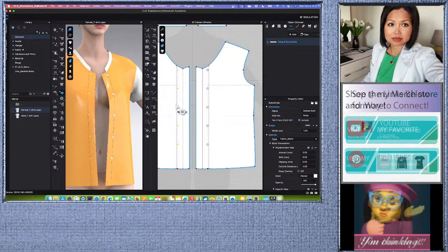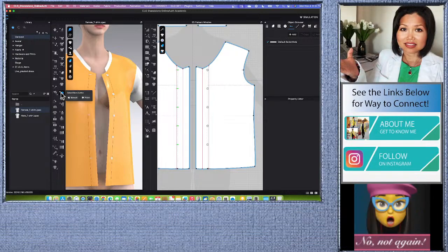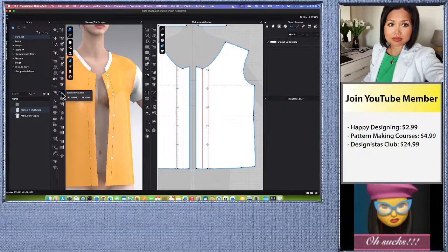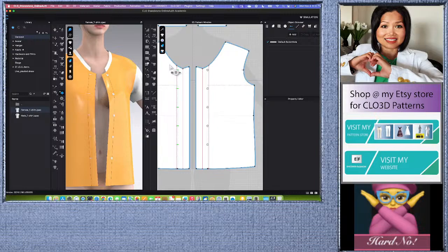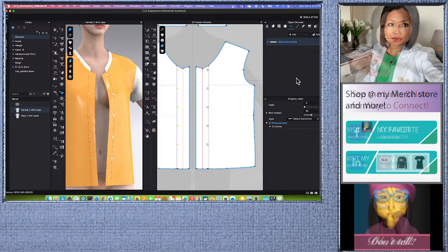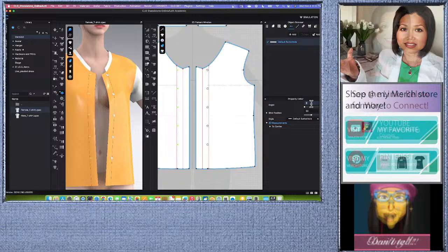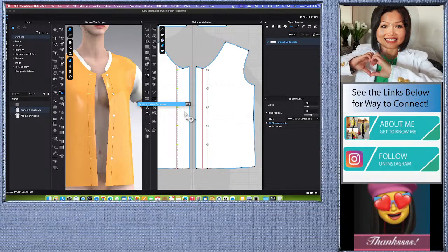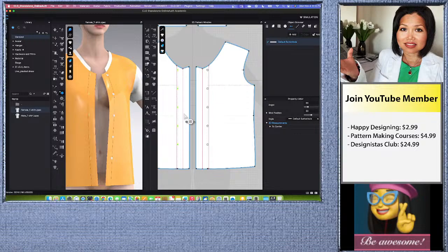All we need to do here is click once on the page to deselect. While this tool is active, you see right there, the select button tool, the edit button tool, active, we want to key select all these, just like that. Then I'm going to come over here to the property editor, and right here type in 90 degrees, and then press return or enter on the keyboard, and boom. Okay, wait for my computer to sync, guys, sorry. It's a little bit laggy when I've been using it for a while.